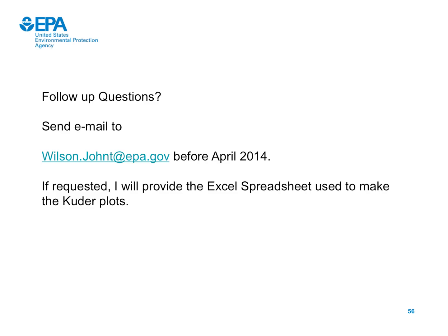You can watch that anomalous well for a while while you're worrying about the high concentration well. The point of that is you make your decision about active treatment and you focus active treatment on the areas sampled by wells that are not going to meet your cleanup goal by the time you're expected to meet the goal.